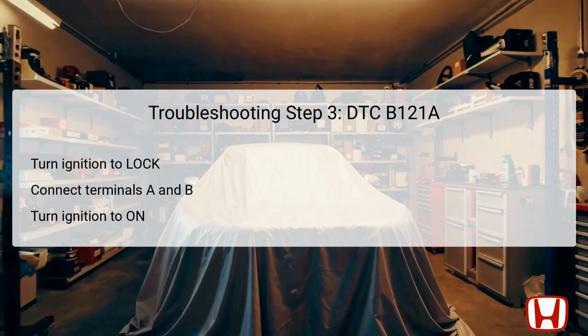The third troubleshooting step involves checking for open wires, specifically in the mode P line. Begin by turning the ignition switch to the lock position, ensuring that the vehicle is off before making electrical connections. Next, a jumper wire is used to connect terminal A from the mode control motor 7P connector, position number 2 for 4-door or number 5 for 2-door, to the body ground at terminal B.